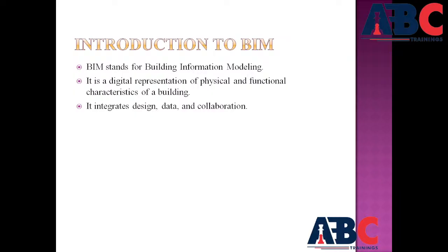So now we will see why BIM is important in modern architecture. Suppose you are using traditional 2D drawings: in AutoCAD you have to draw the plan, after that the elevation, section, and the 3D model. But in BIM it is not like that. If you are doing a single drawing or a plan, it will automatically make the sections, elevations, and different views that you need for your project and your sheet. So this is the most beneficial use of it.